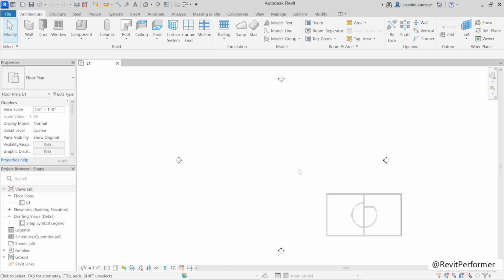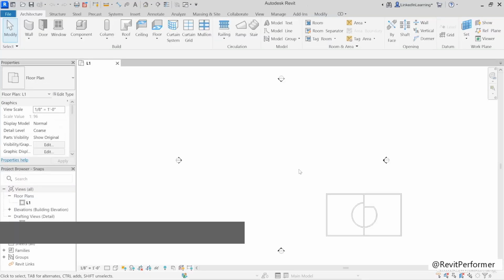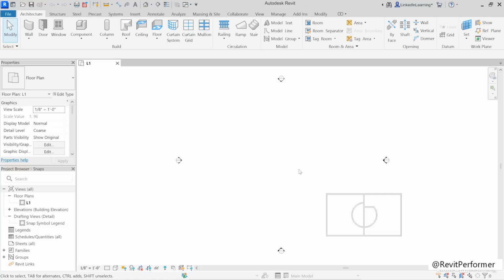In this video, we're going to talk about snap behavior. There are 2 kinds of snapping that we have in Revit. We have increment snapping and we have object snapping. And so I'd like to illustrate both of those. And both of them are similar in function. They help you build your model with more precision without necessarily having to input exact values in order to do so. So let's start with increment snapping.